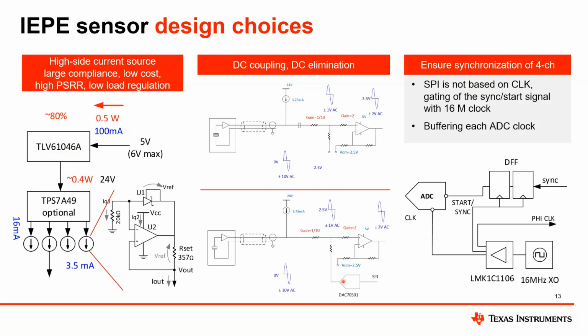which is a 14-bit DAC. The software provided with the design, which you can download from ti.com, has a function to run a successive approximation algorithm to search for the best value of the offset cancellation. This also requires a state of the sensor which doesn't have so much excitation, like in steady state.